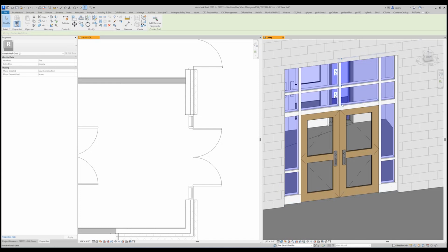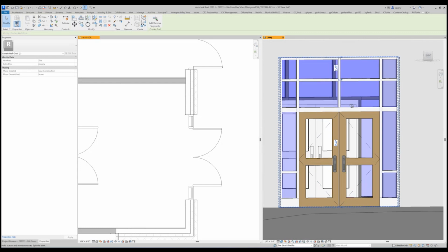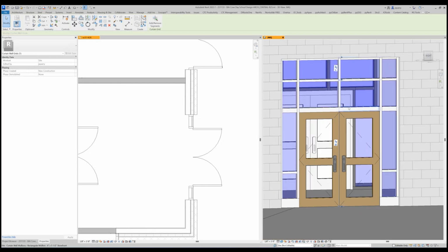That makes sense, because that would not carry a 12'8" line. It would be either 8'8" or 9'4". Let's see, the band on the outside of the house, the top of it, is at 9'4". So this dimension here would actually be 9'3", and that'll put the top of it in line with that coursing.